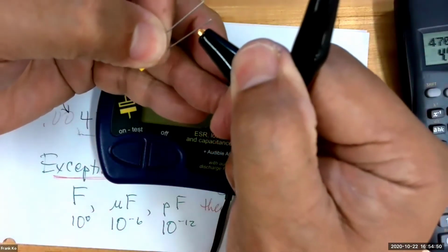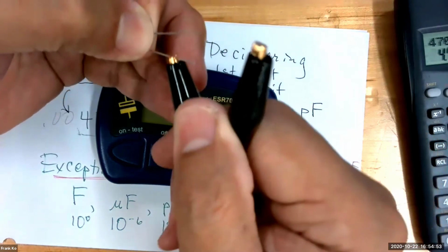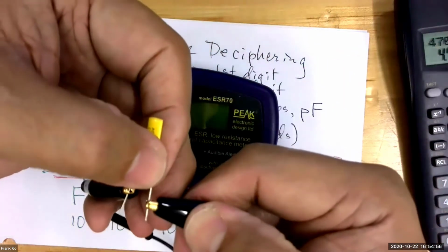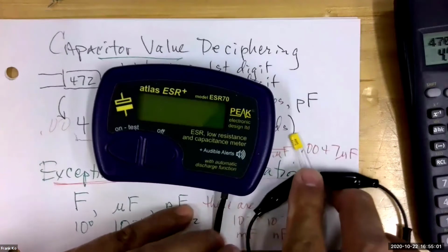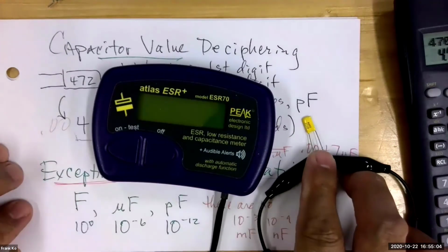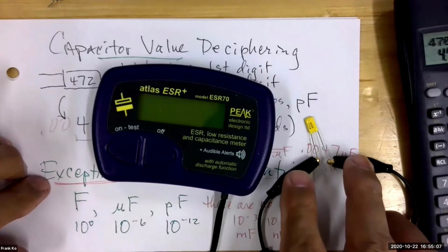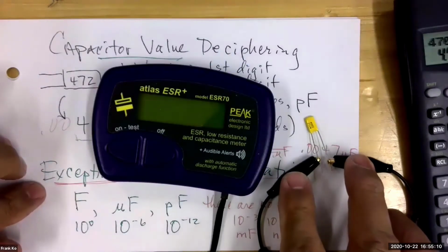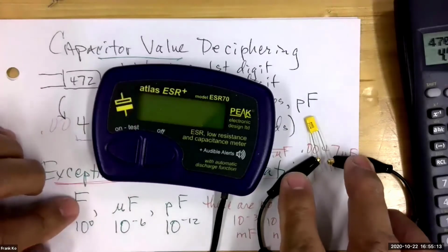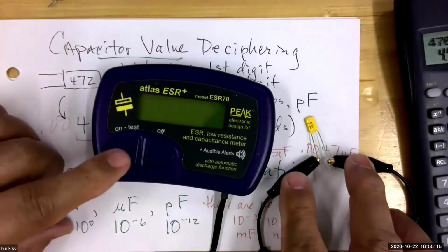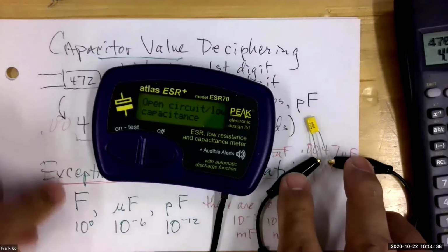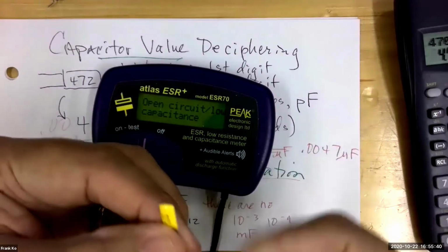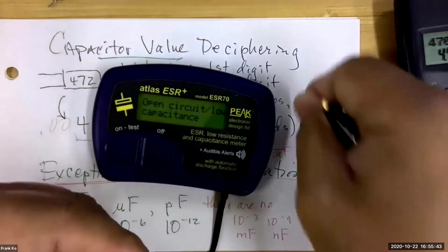And sometimes capacitors are notorious for being marked something, and they actually measure out to something else. This one, I believe, is a good capacitor. Looks like a quality manufacturer. And let's see if this guy works out anything close to 4,700 picofarads, and whether this conforms to the capacitor standards of value test. Yeah, it's too small. Darn, can't test this particular one. However, I did grab a couple of other ones just to show you that the meter does work.